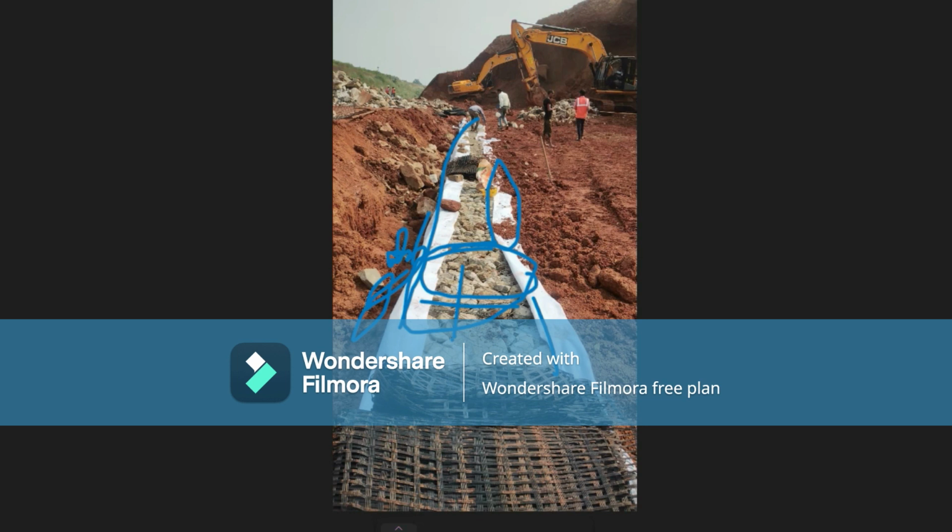It also protects against seepage, keeping the gabion box permeable if any pore water or seepage occurs. Then they fill the existing materials in every layer and compact them by roller on the side of the slope.